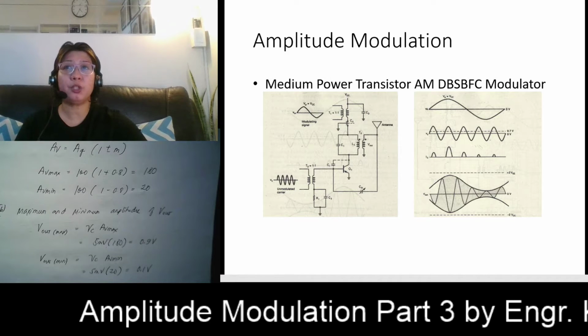However, with the tank circuit, your collector current is no longer dependent on the base drive voltage. The voltage developed at the tank circuit is determined by the AC component of your IC and the impedance of the tank circuit at resonance.